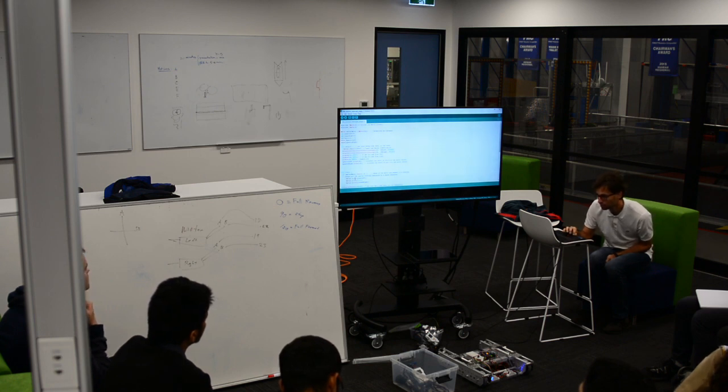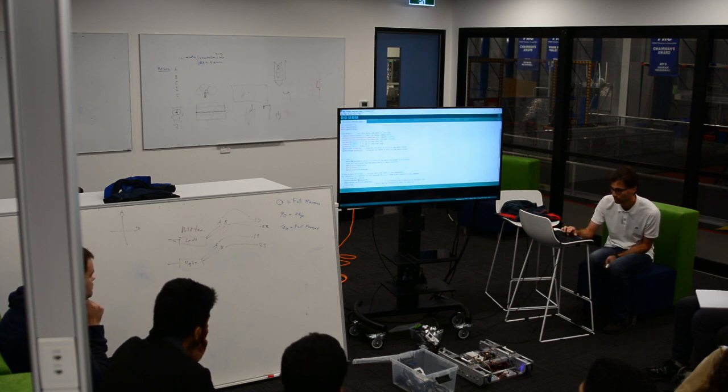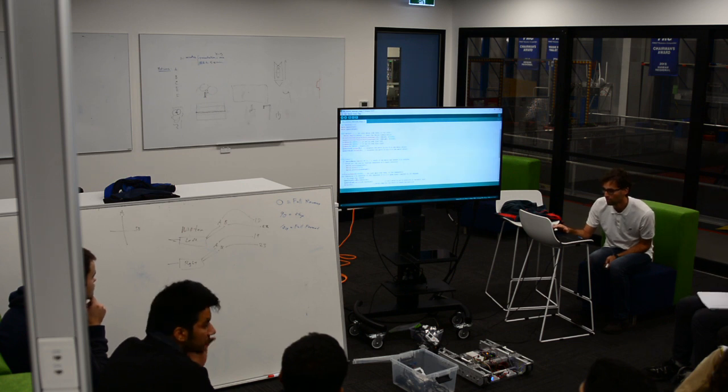So now we can write commands like myservoleft.write. That now means something. It says write the throttle command to the servo on the left. Somewhere in here we're going to have to define that the servo is on certain pins: myservoleft.attach, so it attaches pin 4 to this servo. And we'll leave that out of it for now.